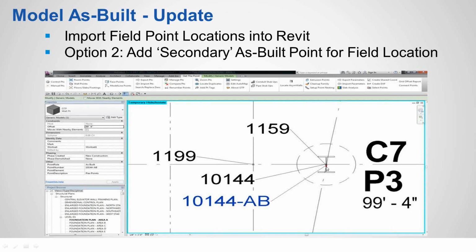So one could be slightly out. You can see here we've got 101.44 for the design intent model, and then we've added a suffix to the end of that 101.44 for the as-built. So it may be just slightly out for the as-built, but we've got this accurate field data which we can bring back into the authoring model. So again, it's another great way to capture as-built information and bring it back into your design model to review.